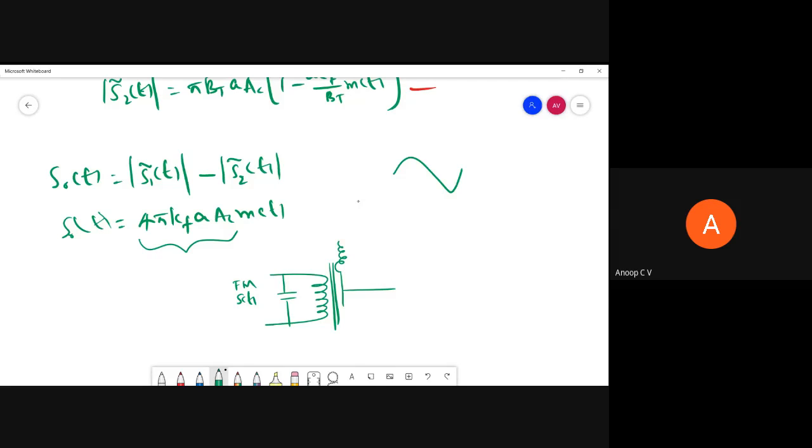We should have a primary part, with two parts, the upper part of primary and the lower part of primary. Then here we should have a filter, followed by an envelope detector. The envelope detector is a diode. So this is a slope circuit, and this is again a slope circuit. This LC part becomes a slope circuit.